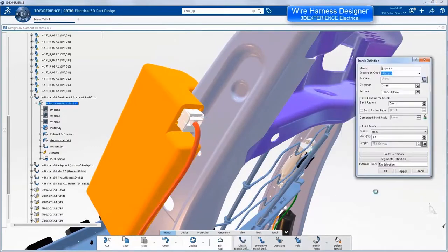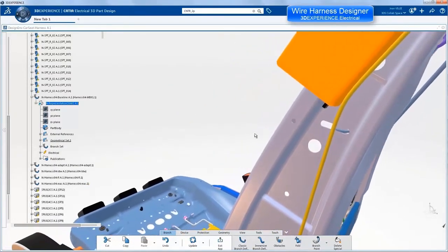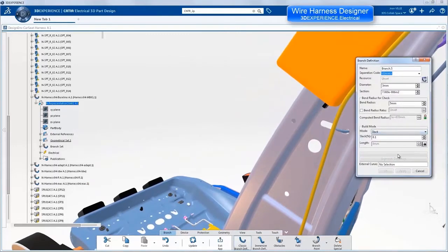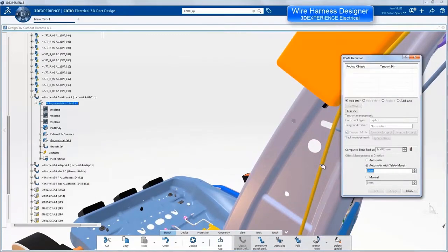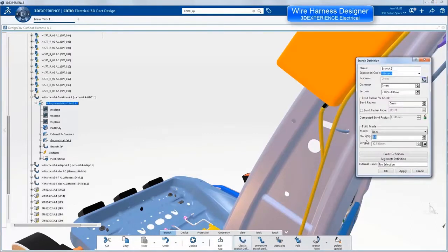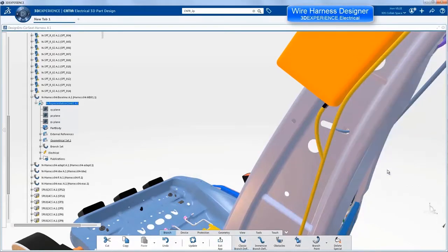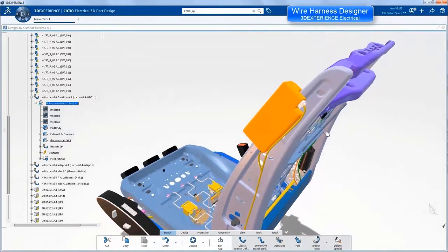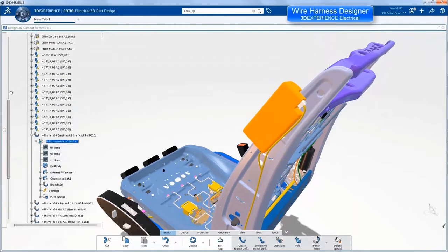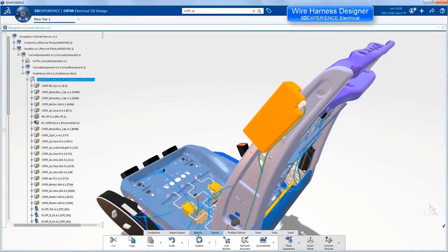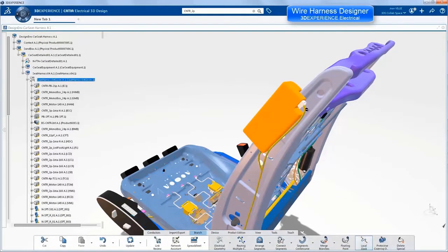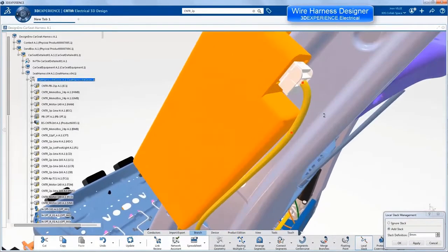We connect to the end of the connector we just placed, and we can add a branch point here from the bundle just created to another connector for the grounding of this airbag unit. We can give it a little bit of overlength to enable the easy connection or disconnection of the cable. And we're going to do the same at the top, using local slack between the two red points, and we want an overlength of 2 mm to make it easier to disconnect the cable.